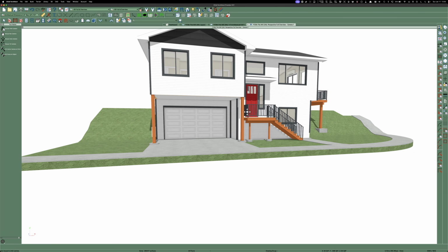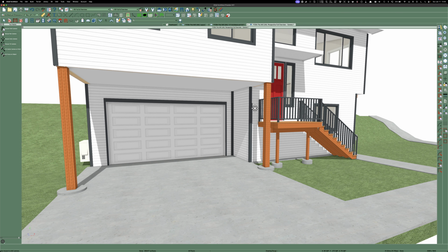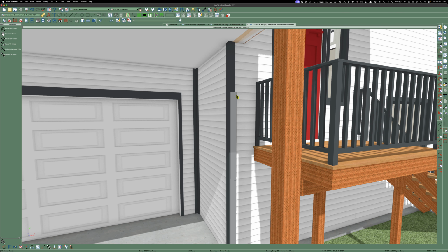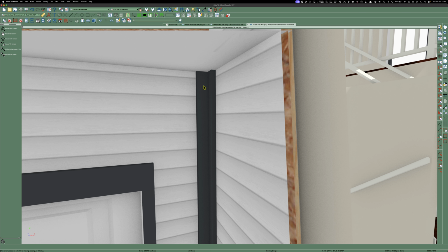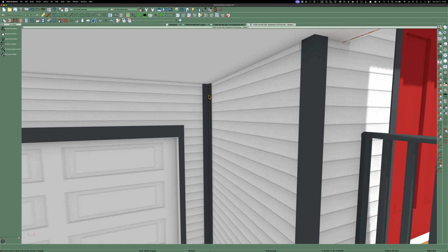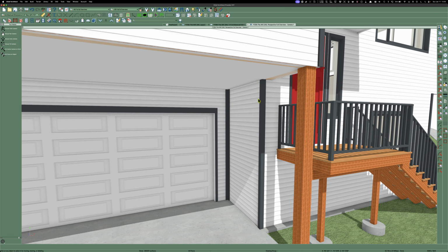And I've never really had easy luck. I'm just checking some stuff here. Why are there 2 corner boards here? That's different. And the other question I have is, we never run corner boards on the inside like this. So I'd like it if Chief would let us, when you have an inside corner, what you do is you nail a 1x1 or a 2x2, depending on how bold you want that. We do a lot of 5/4, which is technically 1 inch trim out here, so it sticks out, it's thick.